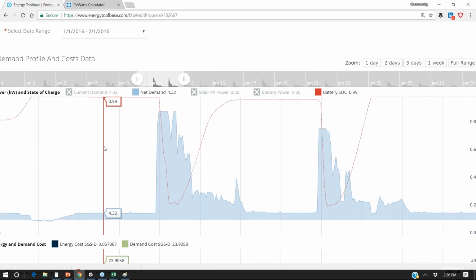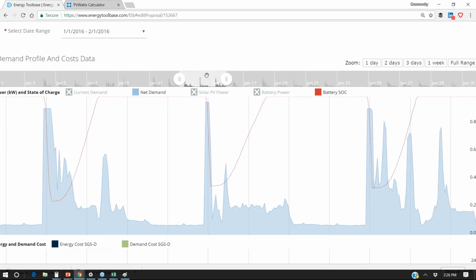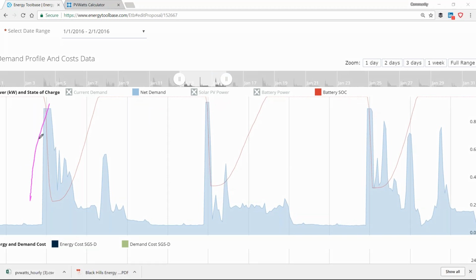And what we want to look at is what are days that are risky of the battery running out of power. And so we see here the battery's at 23%, and we just get through the tail end of the day before the demand starts to slack back up and the battery's able to charge back up from solar. And so this is kind of like what an optimally sized battery bank looks like. But look, in the storyline mentality, there's still some room to grow because we are still seeing this spiky kind of power curve. So what we could do is double the size of the battery bank.